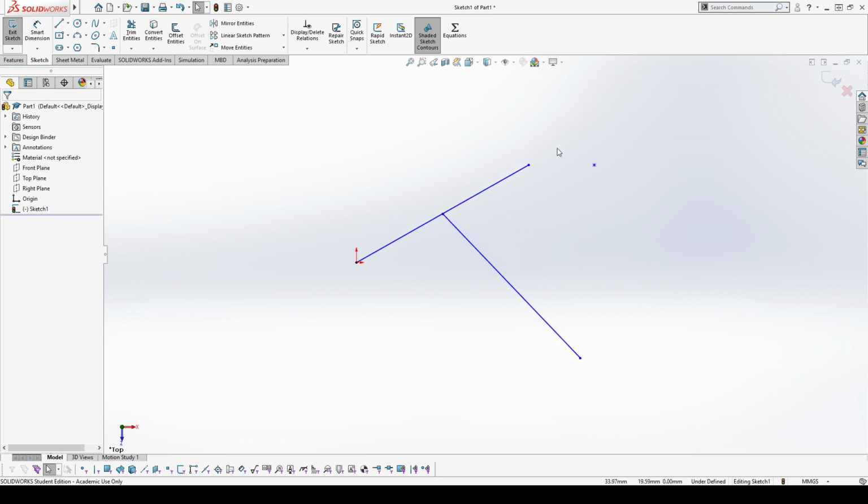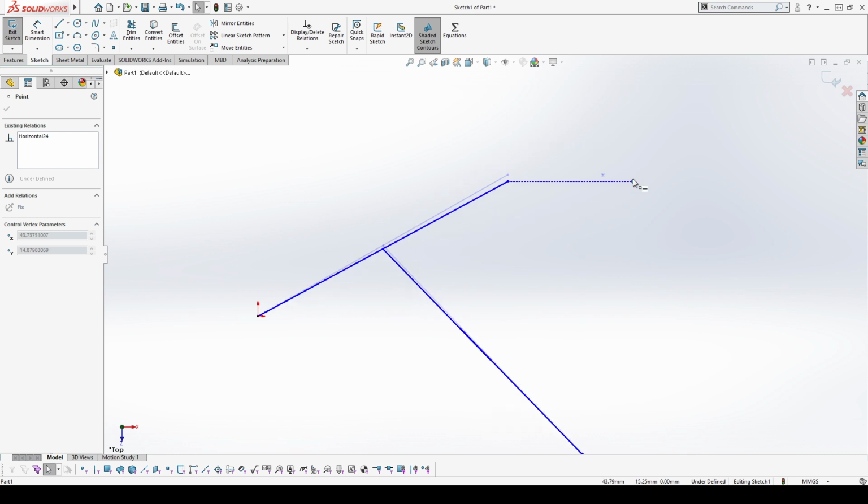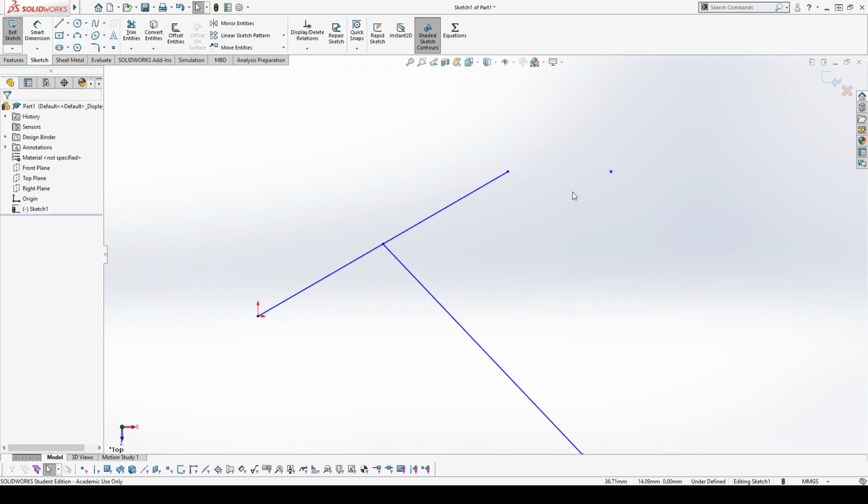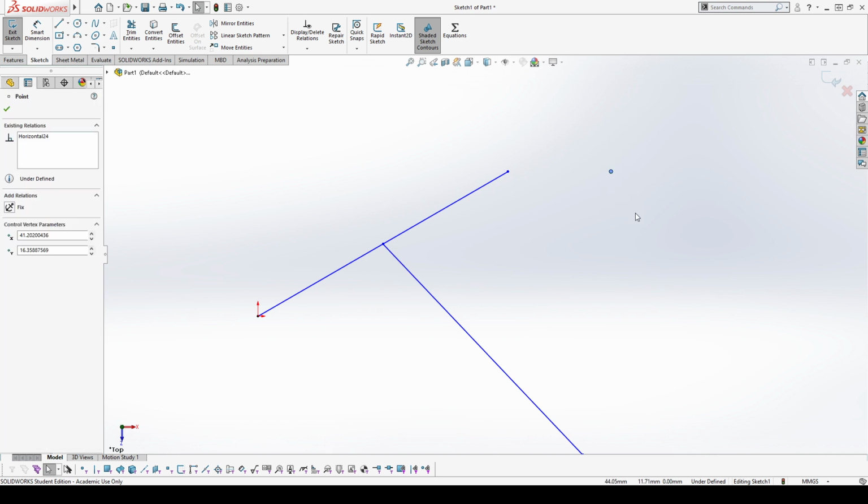If I just open up this sketch and it looks like this, and there's this point just floating here, I don't know what it's referencing when I start dragging stuff around. I mean, when I drag stuff around, it kind of shows me, oh yeah, here, this is horizontal to that. But it's better practice to actually go through and draw in the construction geometry, so that you have that visual cue that, hey, this is pointing to this other point, and then this construction line is actually what's horizontal. So since both those points lie along the line, of course they're going to be horizontal as well.